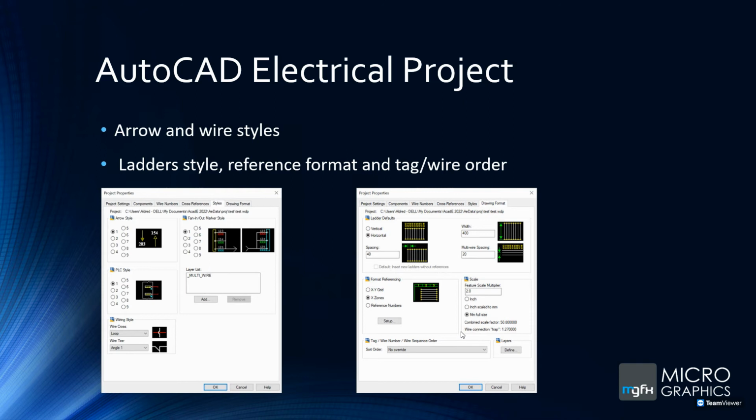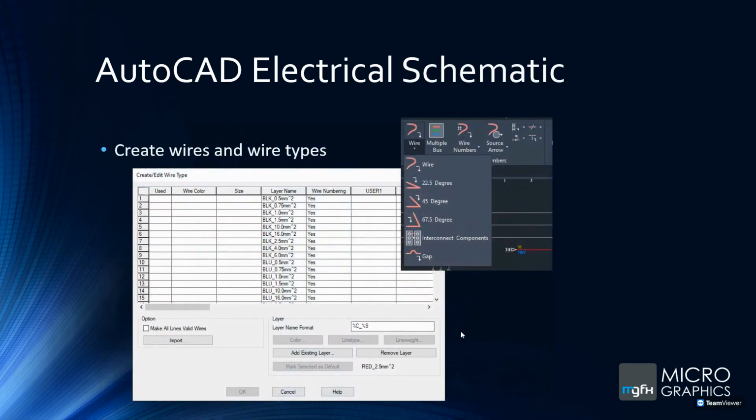Okay, so you can see there, by creating this project, there's a lot of automation that's going into it before you even start drawing. And as I said, you can also then go and override that project properties with the drawing properties of an individual drawing if you just need something to be a little bit out of sync. Okay, so that's the project aside.